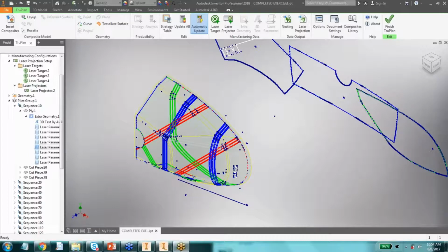And in that way, you're taking manual override, and you're now controlling what those lasers have the ability to do. That can be a good thing because you can force it to overlap or force it to do different things, but it can also slow the system down and increase flicker, because normally the laser projection system is good at distributing those based on where the normal vectors are. So normally we would recommend you leave it all in one file and allow the laser projection system to break down that contour into smaller pieces for each laser depending on where the normal vectors point with respect to the projector.